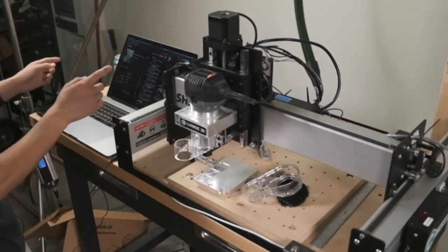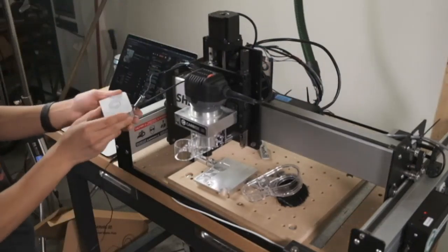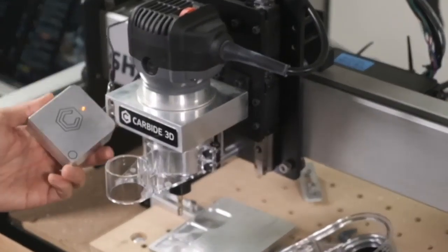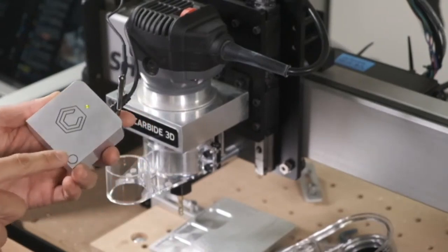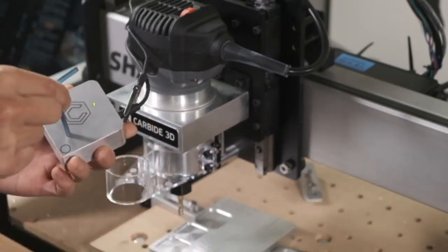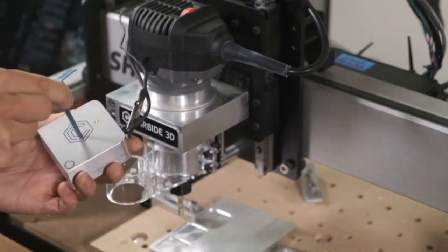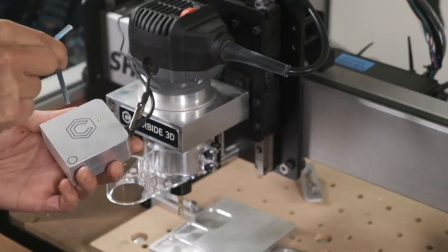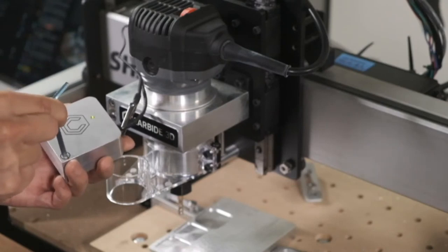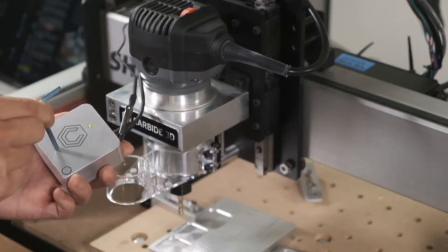When probing only Z, do you have to have the bit hit the little circle, or can it touch anywhere else on the probe? So for those of you that don't know, there's a little target circle here. Let's zoom in again. The reason that circle is there is when the end mill touches off on the top of it, if you're probing X and Y, it's going to do this. And if you start too far in, it's not going to clear the edge before it smacks into it. So you're just going to stab the end mill into the top surface. So that circle is there to give you a reference for where your end mill needs to be so that when it moves over and down, it doesn't plunge into your bit zero.